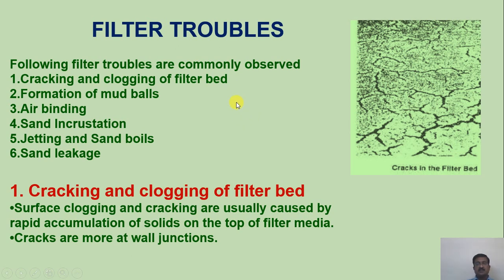In spite of taking all the care, sometimes we have to face some filter troubles, so understanding them is also very important. If you are observing the filter operation in the proper manner, it is quite possible that we may not face these troubles, but in spite of that, we will have to study all this. So what are the filter troubles? These are cracking and clogging of the filter bed, formation of mud balls, air binding, sand incrustation, jetting and sand boils, and sand leakage.